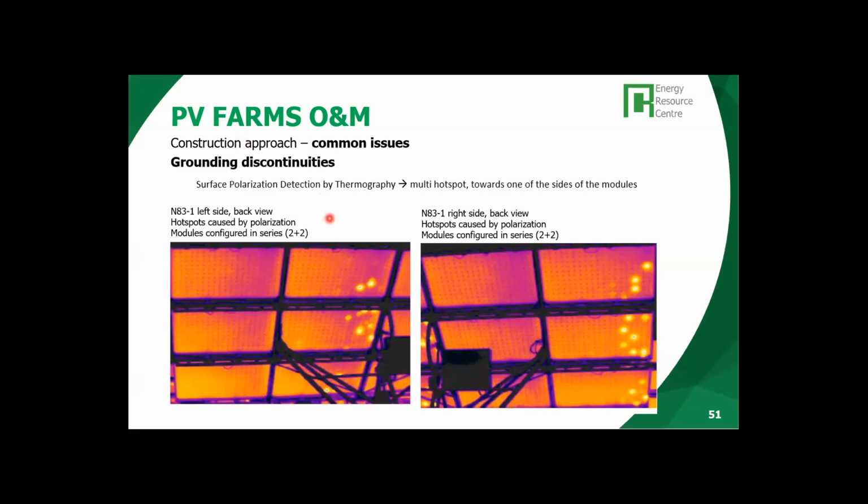Yeah, probably a defect that cannot be detected easily. Yes, as you said, the SCADA system in this plant was not ready to detect this kind of situation. So thanks to the operator, the person who was checking the output performance of the inverters, this unbalance between the phases of some inverters was detected.